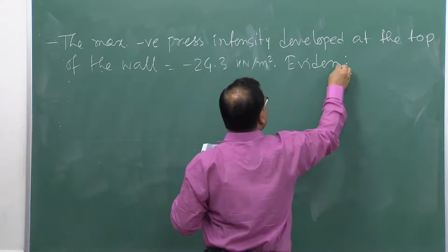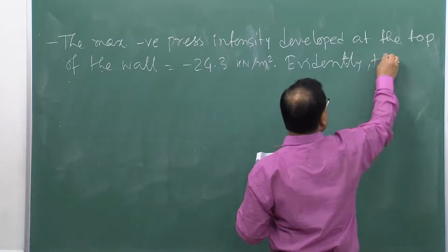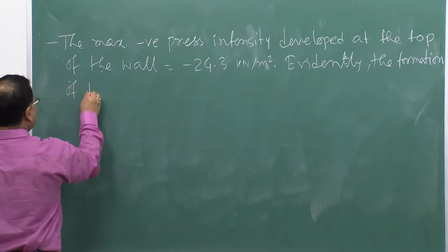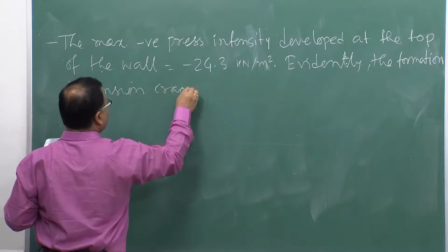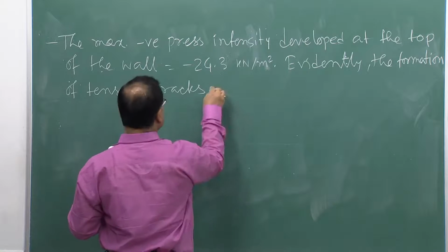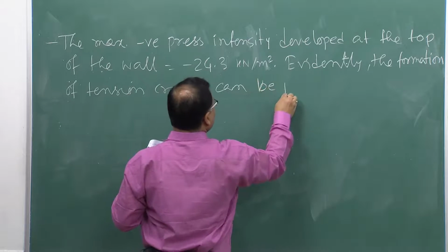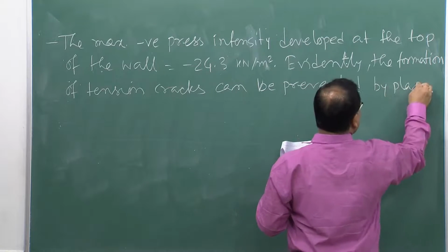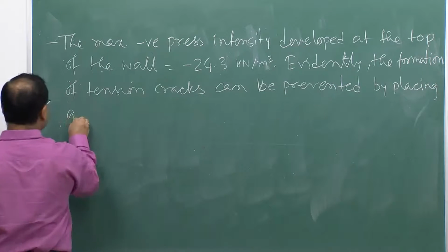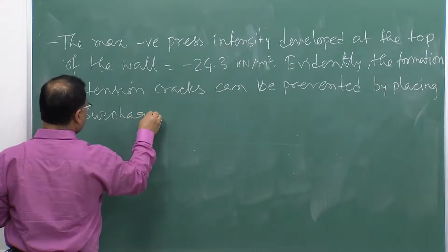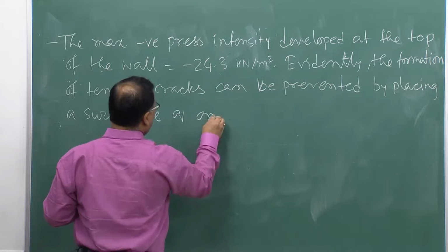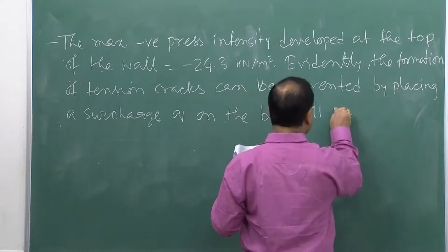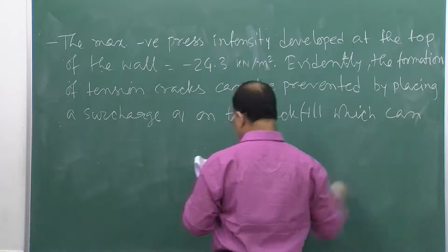Evidently, the formation of tension cracks can be prevented by placing a surcharge Q on the backfill, which can neutralize this negative pressure.